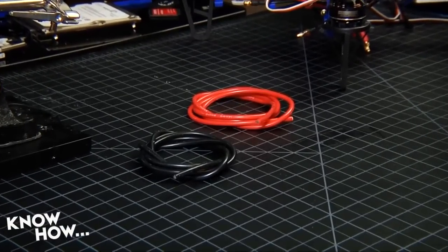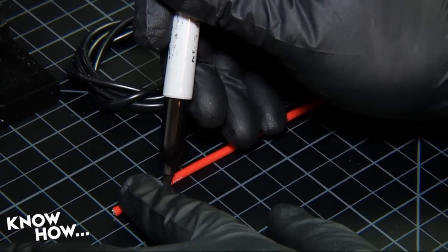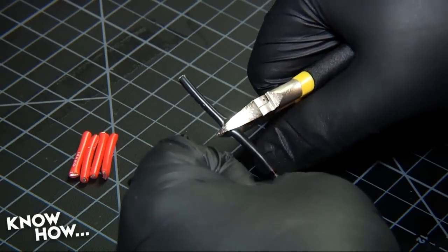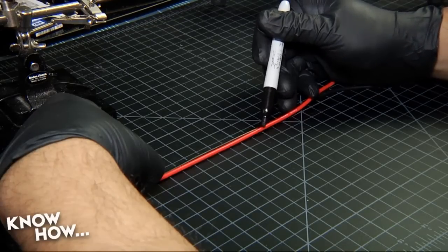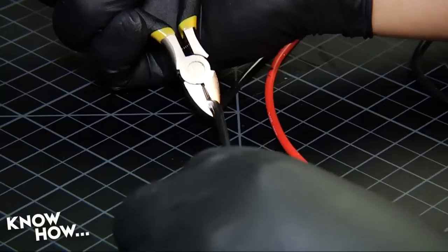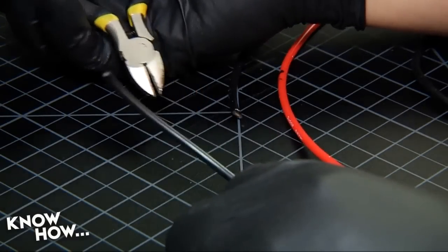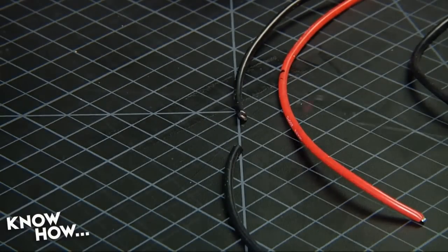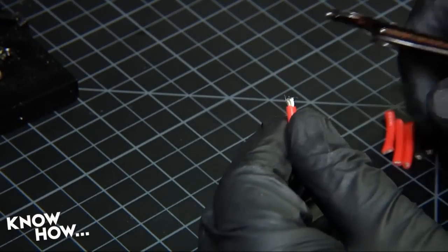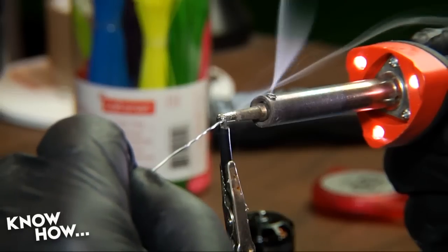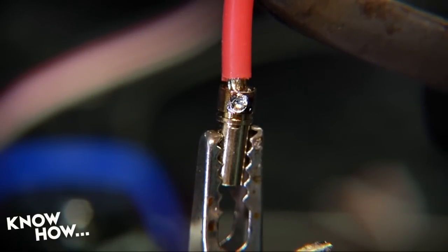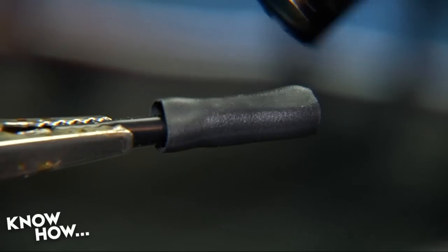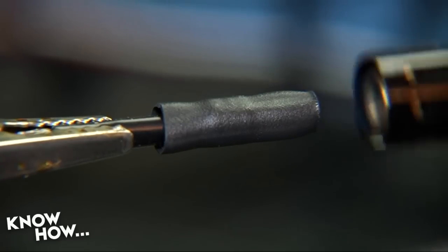Cut 8 1-inch lengths of 14-gauge silicone wire, 4 black and 4 red. These will become the leads that go from the distribution board to the power leads on the ESCs. Also cut a pair of 5-inch lengths of 14-gauge silicone. These will become the wires that connect the power distribution board to the battery. Strip 4mm of insulation off each end of the 1-inch wires and tin each end. Solder a 3.5mm bullet connector to the end of each wire, then check and insulate each connector as you did with the ESC motor leads.